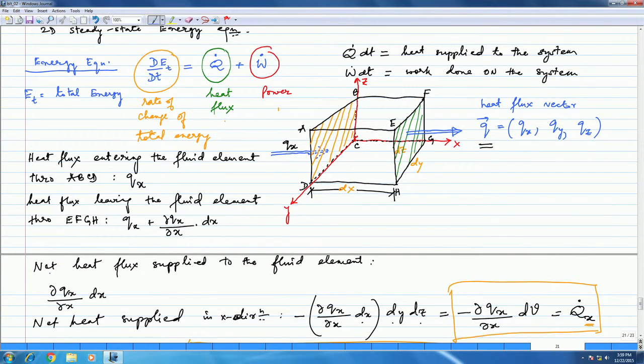So what we are doing now is going right near the wall and taking a small fluid element to see exactly what is going on with it. When I say work done, I mean that due to the viscosity, it applies a resistive force, which comes out to be shear stress. The fluid is in layers, and it shears off. So I'm talking about a fluid element, which is experiencing a certain shear stress.